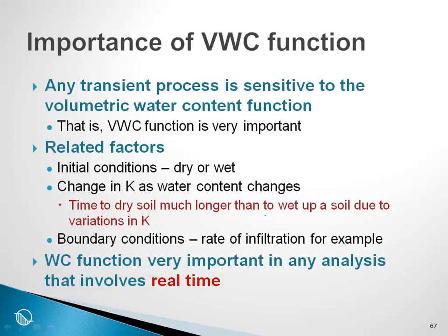For the examples we have seen, the important thing to remember is that the water content function is very important in any analysis that involves real time. If we want to talk about days or years or months, and we want to predict time with any reliability, then the water content function is extremely important. Even in consolidation, we need to define the volumetric water content function, or the slope of the function where the pore water is positive, which is related to m sub v, and is directly related to the real time it will take, for example, to dissipate excess pore pressure due to external loading.